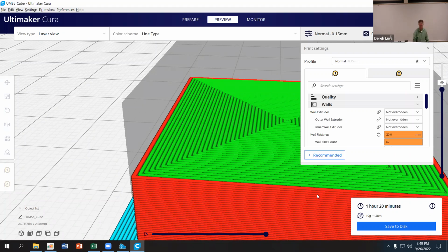And for something like this, where it's not structural, it didn't break or ding or damage or deform or anything. It's just there to keep the components inside it safe. You really don't need very much material. You can see there's some supports on the edge holding up that tab. This was on the build plate, which you can tell it's nice and shiny, nice and smooth. It was on that glass build plate. And then I've got some supports on the inside to keep that bottom plate rigid, because otherwise this bottom piece would be kind of flexible and it wouldn't provide rigidity to the rest of the structure. So I'll put these in there. Okay, pass it down.